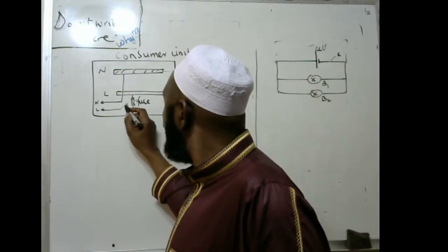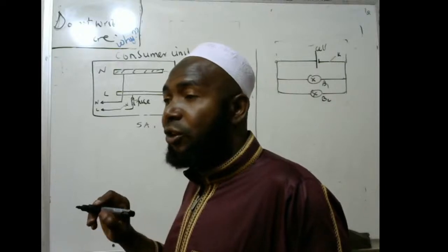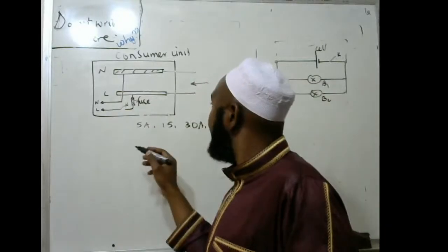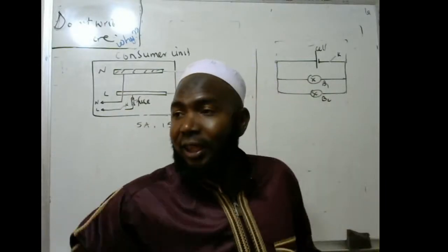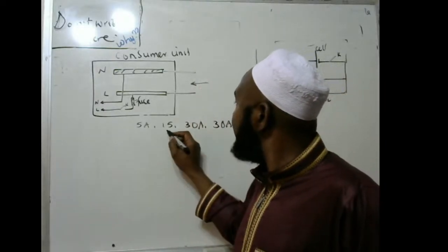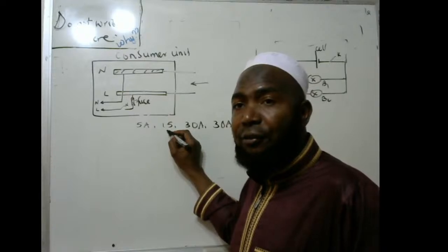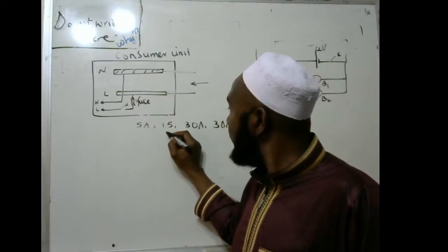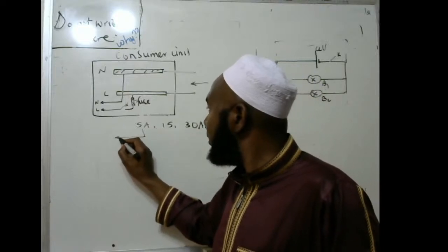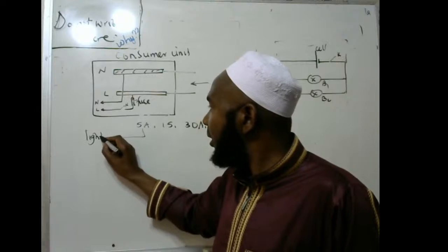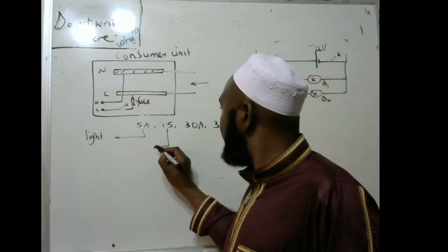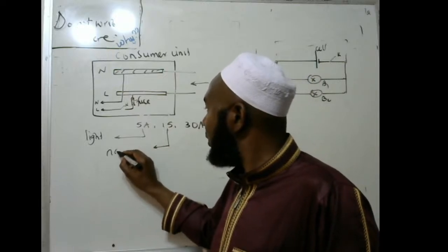You simply open that switch, thinking that they don't use the what? But the lights are on. The lights could be on, but the ring main fuse is not working. Are you getting it? And if you want to connect maybe to the flat iron heater, then you can connect. No, this one is usually for the lights because they use little current. Are you getting it? Then this one is for the ring main circuit.